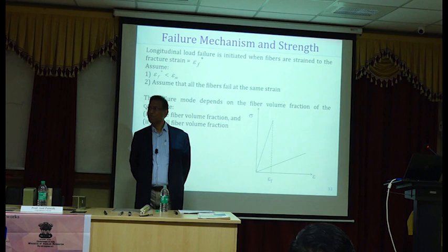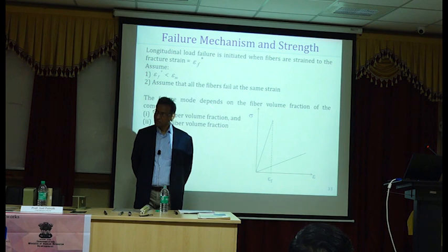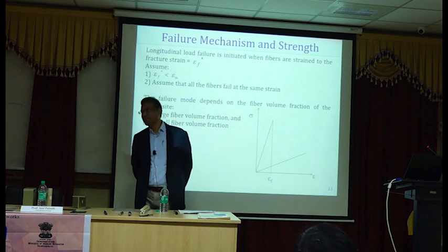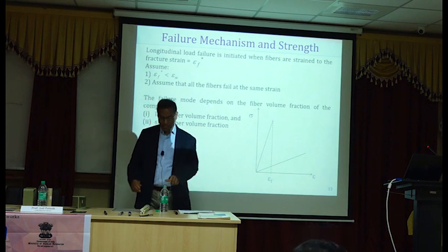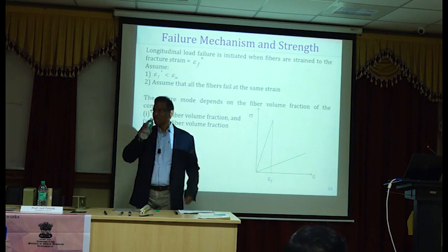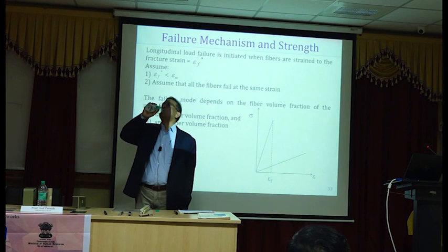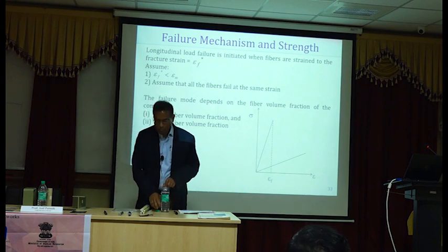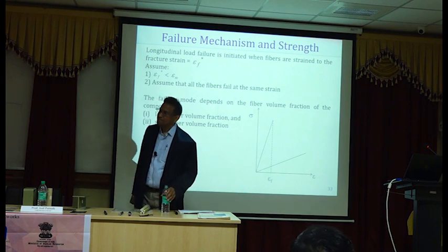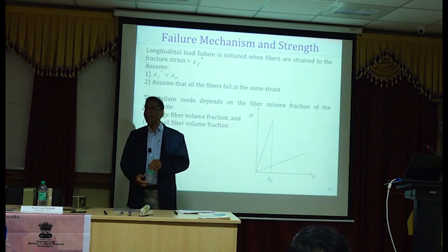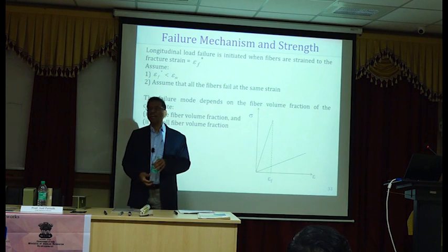No, don't, no, that's providing minimum tensile strength for the concrete, that much minimum steel is required. I think you are going in the right direction, but I'll explain it. For example, if we are providing 0.12% of PD, it means that is the minimum required for providing tensile strength for that section. Okay, all right. Any other thought? That's a good one. You are going in the right direction. Any other way to explain it?